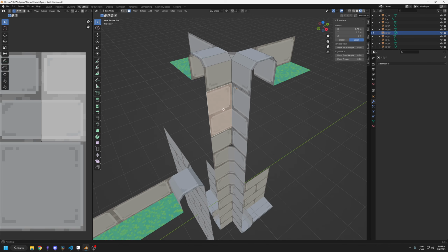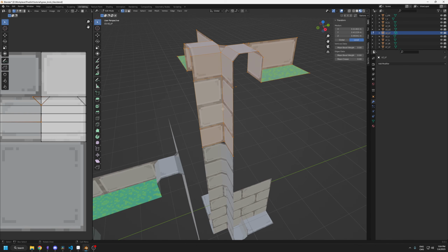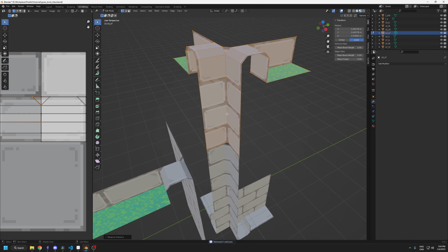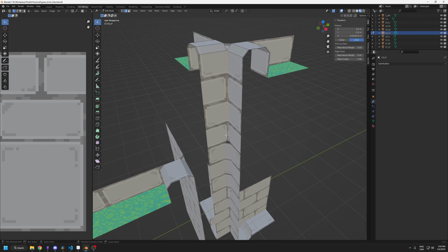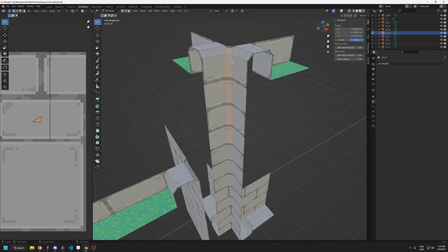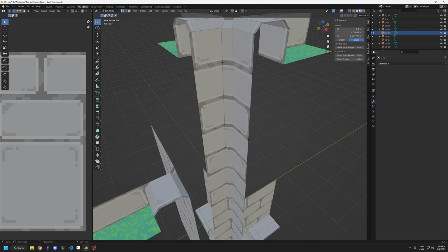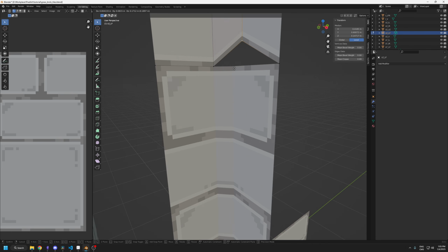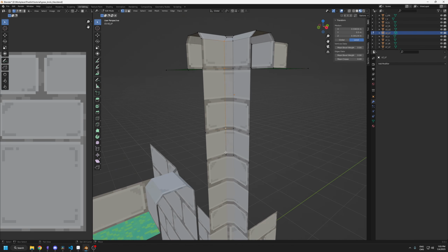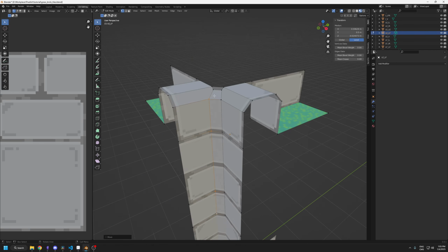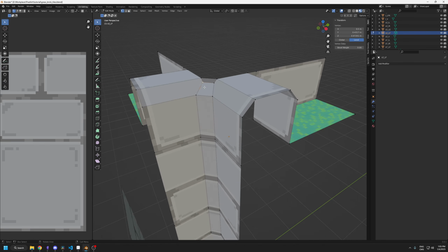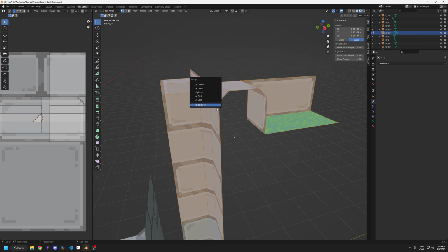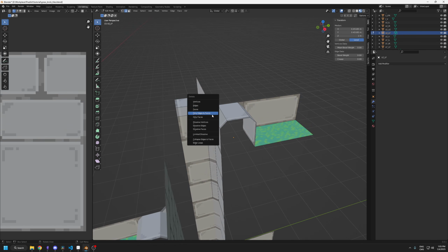Then I'll go in edit mode, select all the vertices, merge them by distance. I'll select the edges and then Control B, and I'll go approximately, and I'll select the vertices. I'll activate the snap to vertex and just move and hold Control and snap it there. Pretty good. I'll do the same for those. All right, here I'll double tap the G and move the vertices up, and I'll merge them. All right, so this tile looks pretty good.